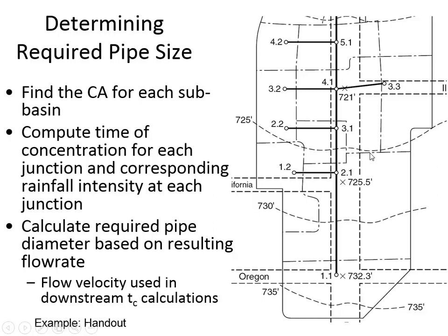Sometimes these boundaries are a little bit artificial. They're probably taking into account where the break lines are in elevation, if there's a high point in elevation. It might be based on if there's a curb somewhere. The curb can force flow one direction that it might not ordinarily go. Different surfaces, like if there's a concrete sidewalk, can intercept flow and redirect it a certain way. But somebody here has already done the job for us of identifying what contributing area goes to each of the inlets.